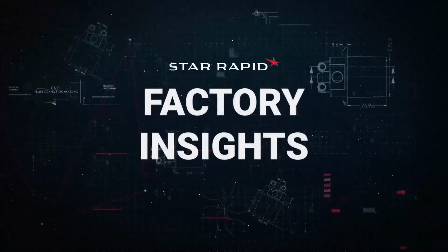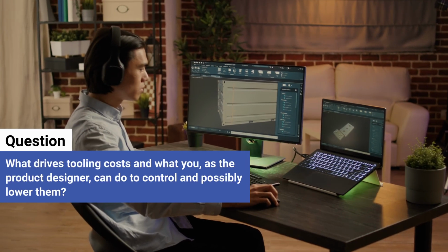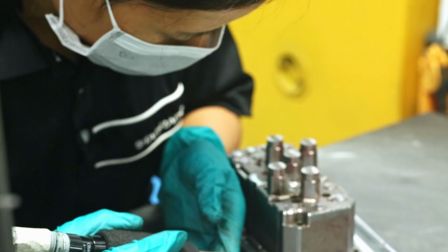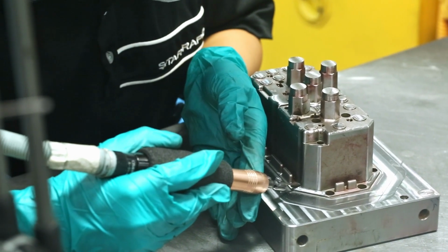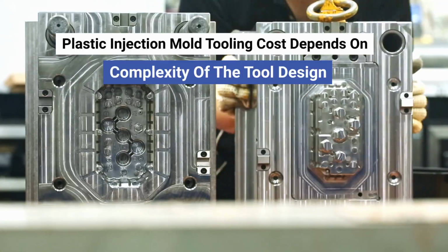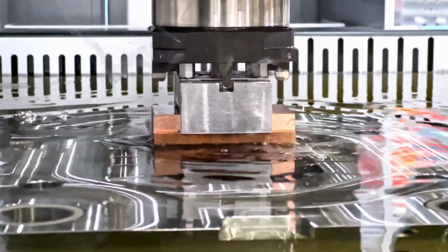In this episode of Factory Insights, we thought it would be helpful to offer a few tips about what drives tooling costs and what you, as the product designer, can do to control and possibly lower them. The cost of a plastic injection mold tool is based on four main drivers: the tooling raw material, the size of the tool, the complexity of the tool design, and the time it takes to make it. Let's look at each of these a little more closely.